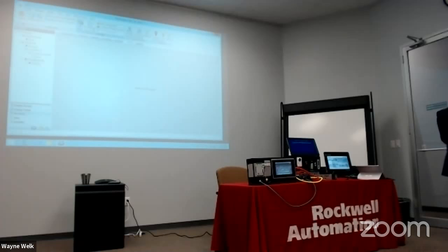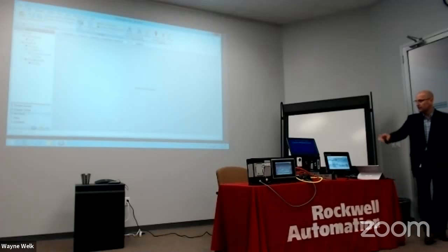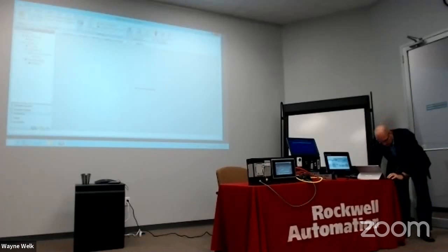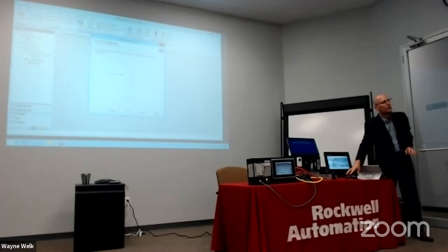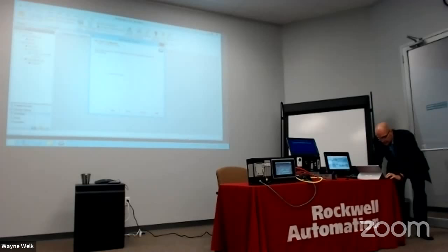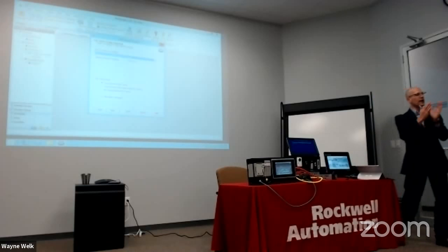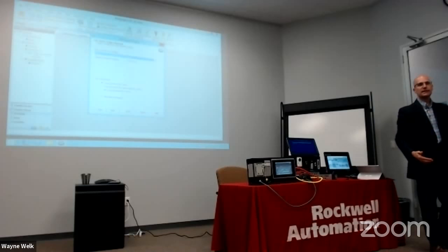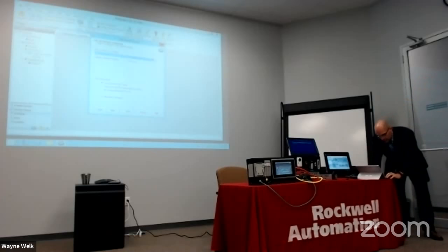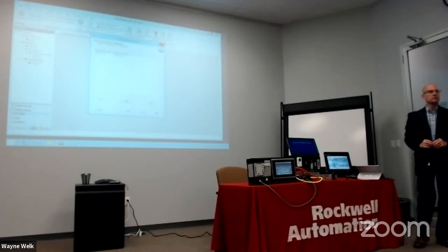I'm using what is called PXE, pre-execution environment. There's a PXE server within ThinManager. You're communicating there. It's a checkbox right up here. By me checking that, it's allowing it to look for a device that has no OS. This is not a ThinManager ready device. This is an off the shelf device that you have, or a computer. And what we're saying is that 10.6.10.51 is my server. So my range from DHCP is going to be 10.6.10.110 to 119. When I go here, that's what you see there.